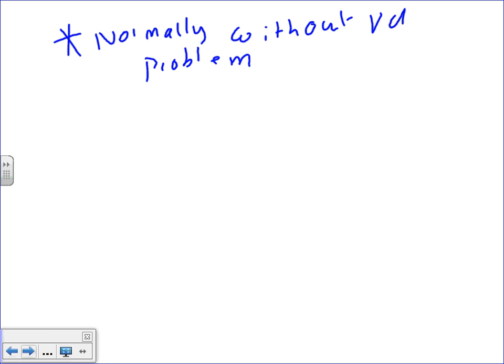Normally, without a voltage drop problem, just 50 feet away from us, 70 feet, we're okay. Let's take the 1 point sizing here. So let's take 1.25. Why do you think 1.25? Motors are considered continuous load. The full load current was 40. What would that give you?